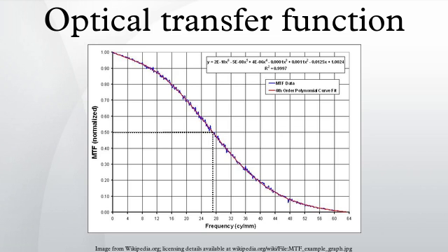Another factor in digital cameras and camcorders is lens resolution. A lens may be said to resolve 1920 horizontal lines, but this does not mean that it does so with full modulation from black to white. The modulation transfer function gives the true measure of lens performance, and is represented by a graph of amplitude against spatial frequency. Lens aperture diffraction also limits MTF.